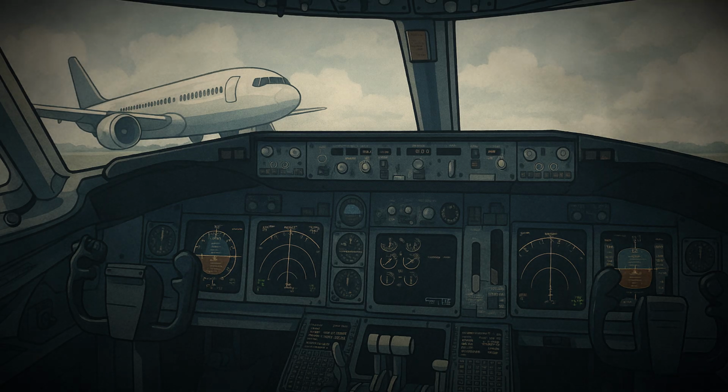Interference drag occurs when airflow around different parts of the airplane meets and disrupts each other, such as at the junction of the wing and fuselage or around landing gear. Careful design of fairings and fillets helps reduce this type of drag by smoothing the airflow at intersections.